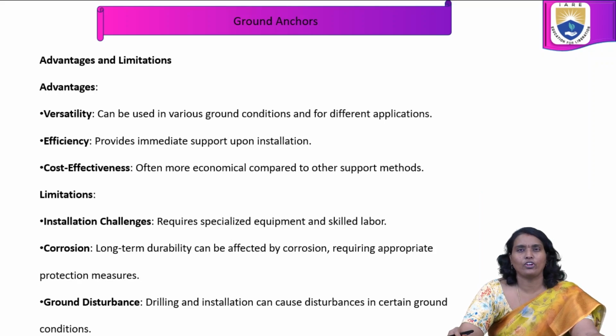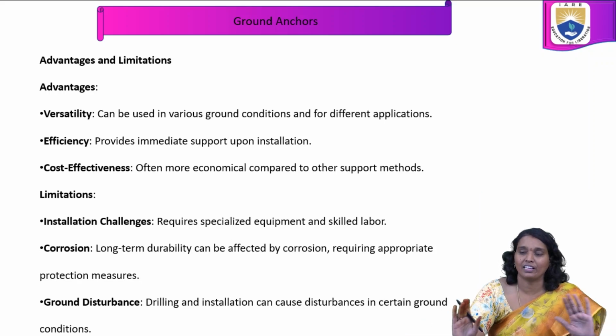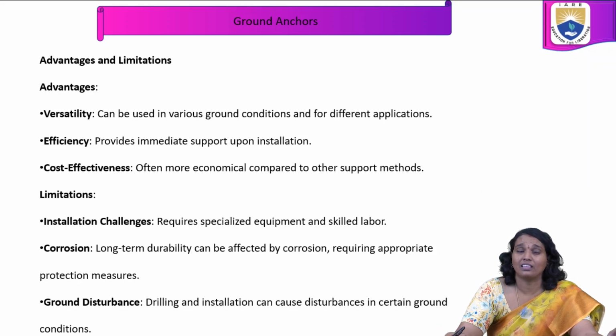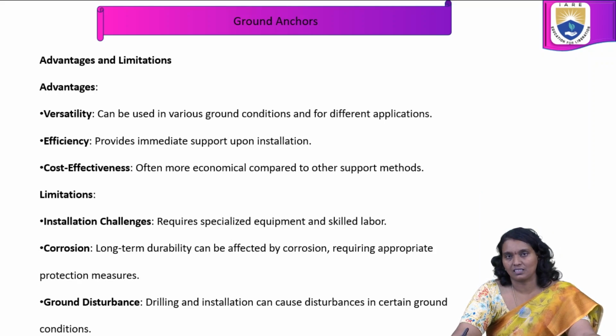From an efficiency point of view, it provides immediate support upon installation, an immediate effect. With these ground anchors, the project time is going to reduce. So we are using such techniques for getting soil improvement, and we want the required desired properties. In those particular conditions, these ground anchors are helpful without affecting the construction schedule. Less effort compared to some other techniques. And also the cost effectiveness, often more economical compared to other support methods.